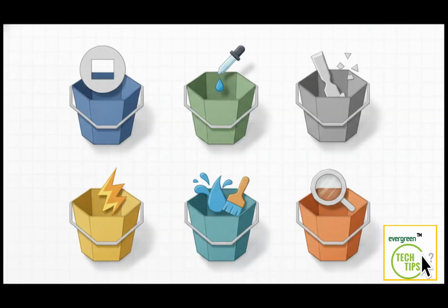So how do you avoid getting completely lost among the 435 multi-million-dollar tools sitting on that clean room floor? Well, as a systems engineer, grasping this beast requires categorization. You've got to group them into 6 core functional buckets: making the mask, adding material, removing material, modifying material, cleaning the wafer, and inspecting the wafer. Basically, everything happening in the fab is going to fall into one of those 6 buckets.